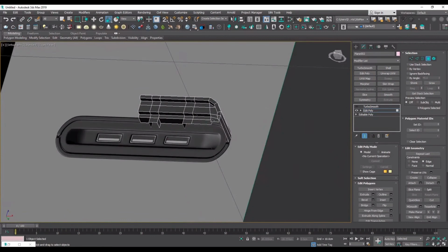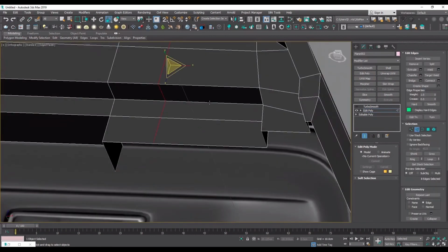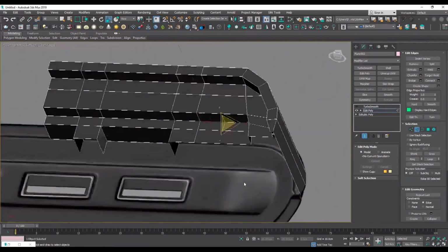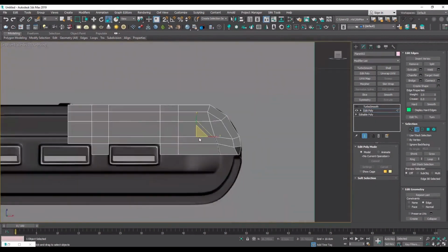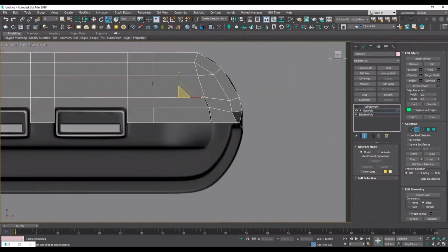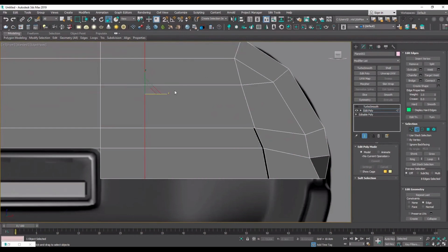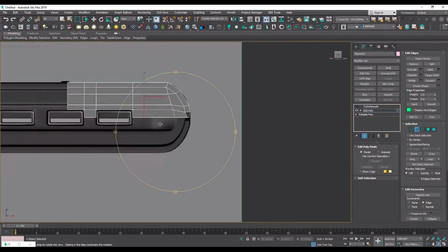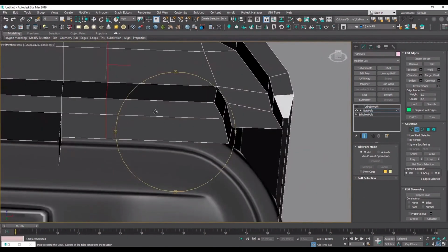And my goal here is to create the sort of bending that I told you, which is just here on these parts. But I have put an edge loop here right in the middle because I don't want a bending to interfere with the other parts of our model. I want to limit it, and this serves as a safe margin.